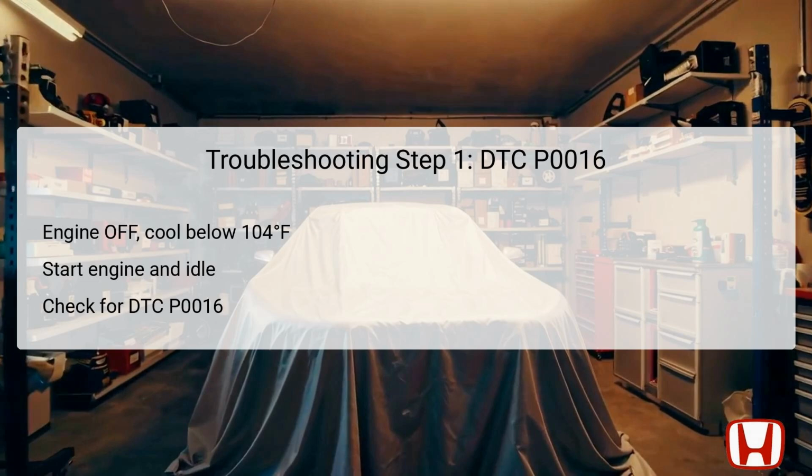During this idling phase, monitor the system's performance for any abnormal indicators. Once the engine has been idling for a few moments, check the onboard diagnostics for DTC P0016 presence. This step helps determine if the problem persists and establishes the foundation for subsequent diagnostic actions.